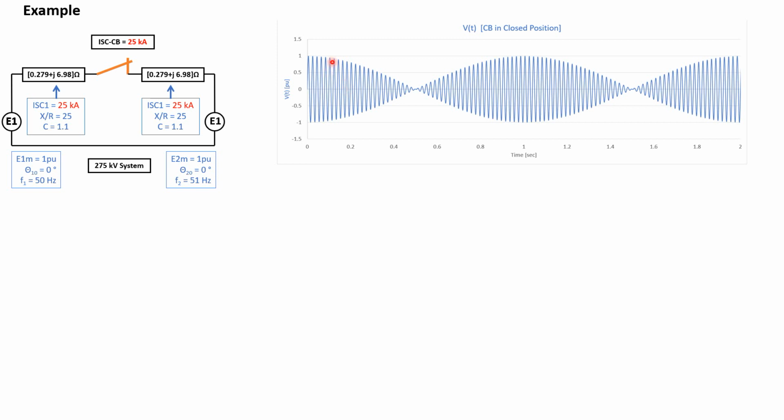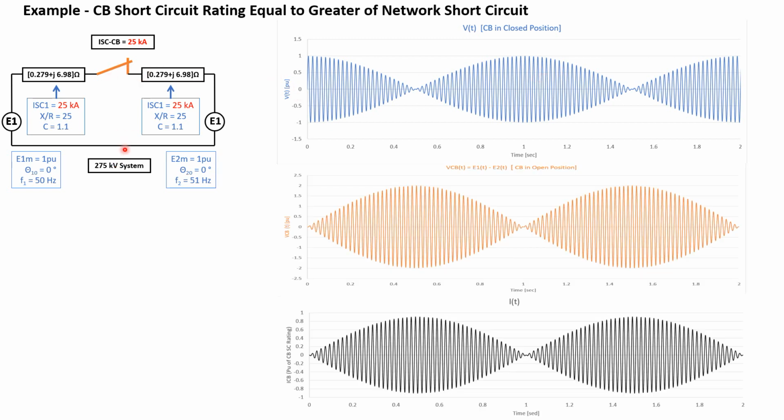That's why we have two frequencies in the system, and it's a strong signature, and very good to know. I have seen many event fault records from the relays that have exactly this sort of pattern, so this means there are two frequencies. And you see it's 1 per unit here, so that's the voltage when you have an out of phase system.